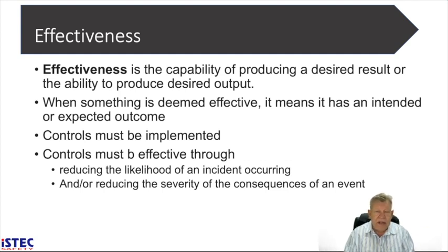We have hazardous chemical substances. One of the common things that I say is we take this MSDS, the safety data sheet, and we stick it up somewhere on our notice board. And this whole notice board is then covered with safety data sheets. But the people that need to read that sheet, they don't read it.